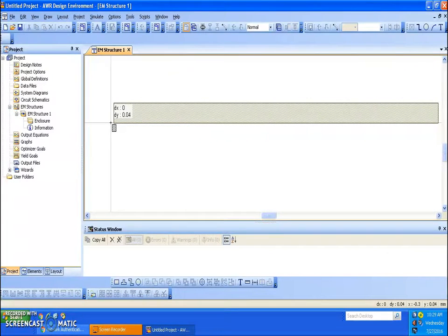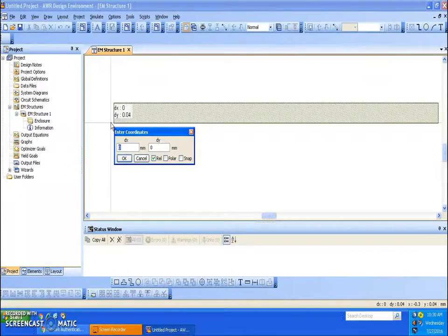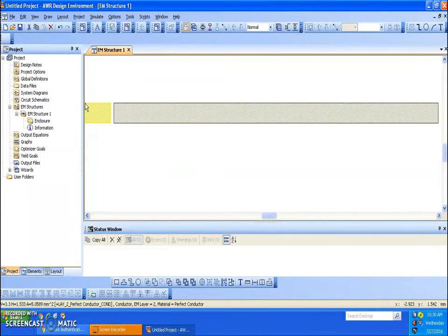And again you need to add the structure width and height, which is going to be dx and dy. For dx you need to add minus 3.3 in the x direction and the y is going to be 1.533. So click on the OK button after adding the feed line. Now you are able to see that the feed line has been added with a space of 0.3 mm from the earlier strip line which we have drawn.